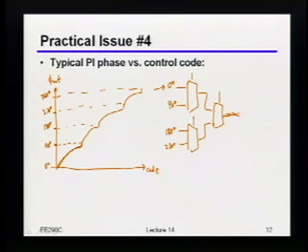Is it because of the selection signal of the second stage mux, that there's a delay between the two? I think that's more of a glitch issue. But there is indeed something that's kind of subtle, which is, you guys are all homing right around where this is. It does have to do with capacitance, by the way. Your delay between the paths is different than when you're interpolating,